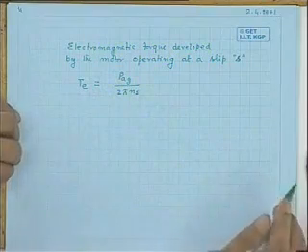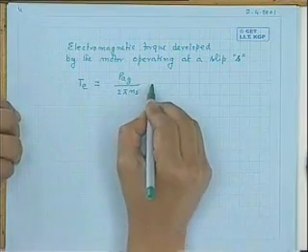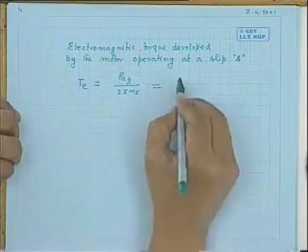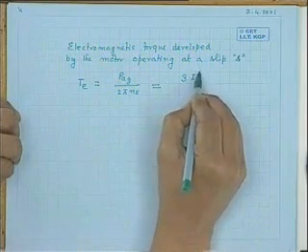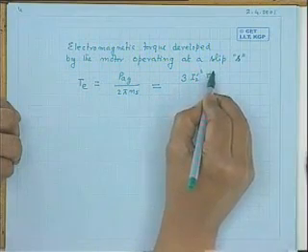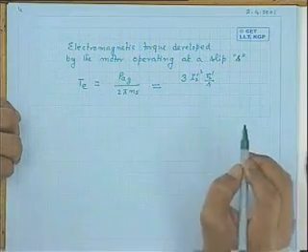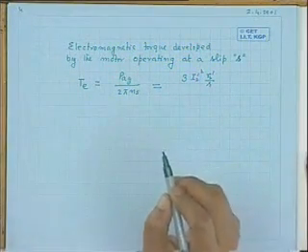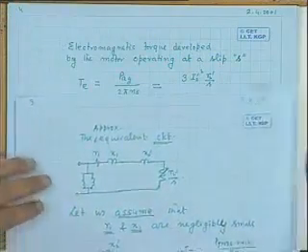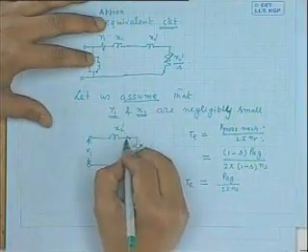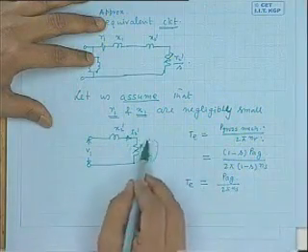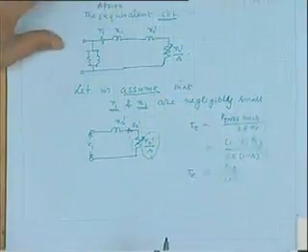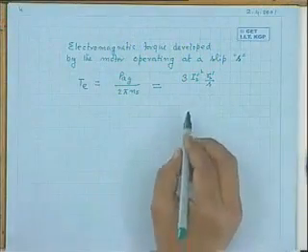Remember, Ns is the synchronous speed and a constant of the machine. Now what is this P air gap power? This is nothing but 3 into the power in the resistance R2 dashed by S. That will simply be 3 I2 dash squared R2 dashed by S, the power here in this resistance.